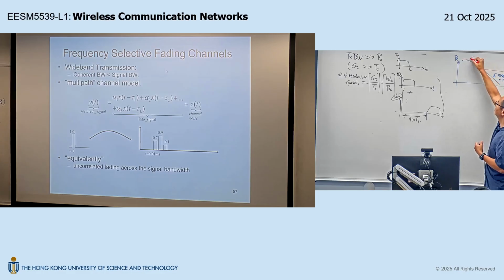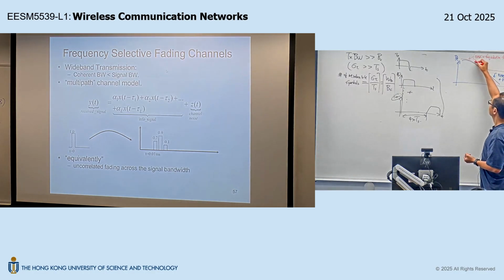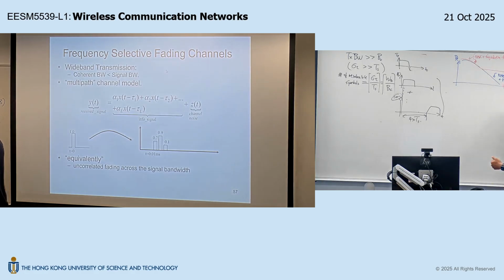So this will be BPSK over frequency selective fading. Okay? So the two-star trouble comes from, first, your error probability is still falling off slowly, similar to the flat fading case. But the second star is here. You have something called an irreducible error floor.